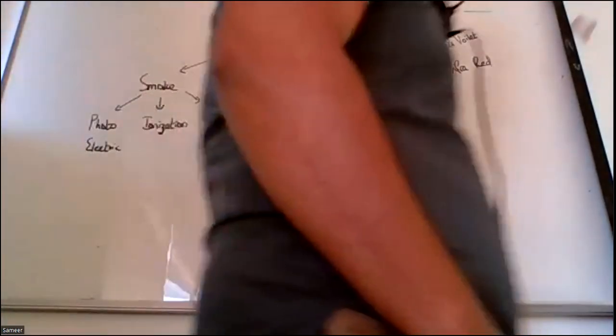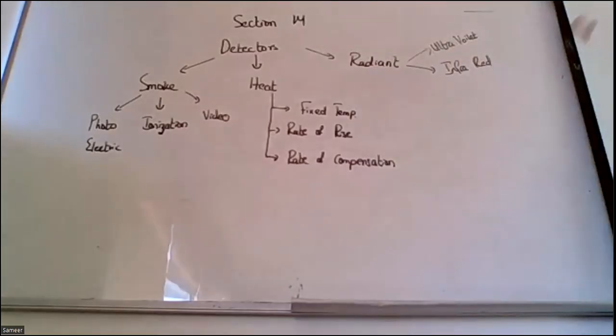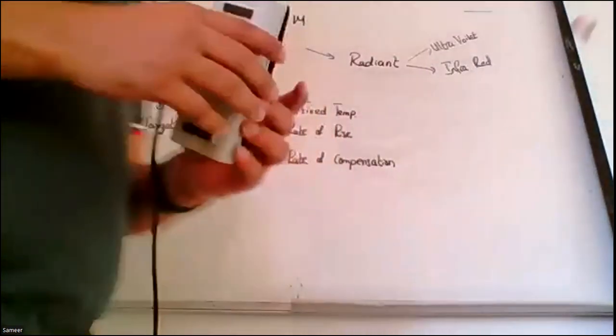One of the detectors that we have not mentioned here as a fire signature is the gas detectors. They are not fire signatures, because they detect toxic or flammable gases, so we will discuss them separately. Based on fire signatures, smoke, heat, and radiation, let's start from smoke detectors, starting from the photoelectric detectors.